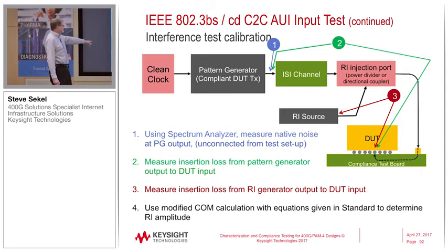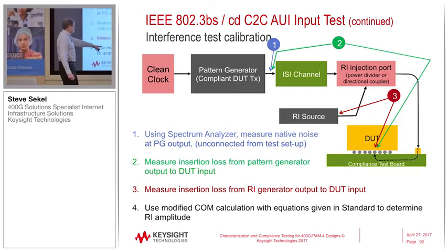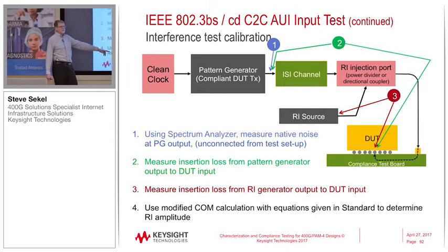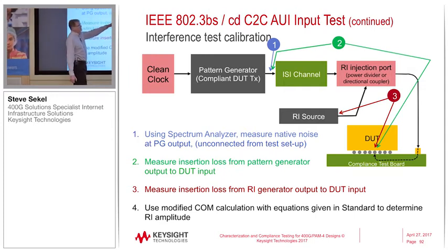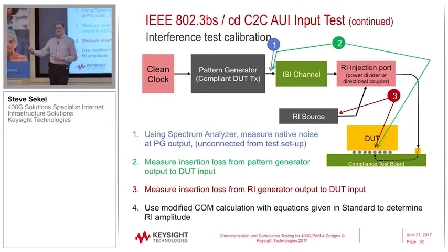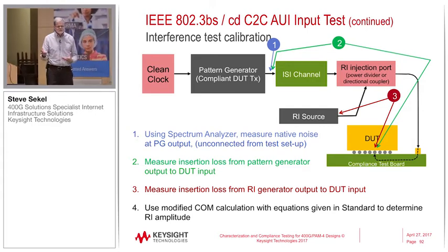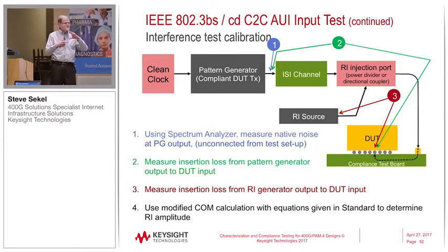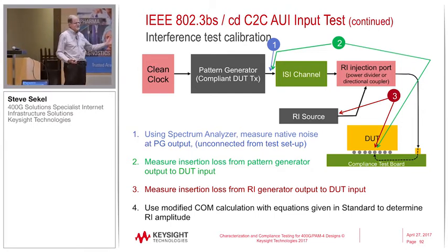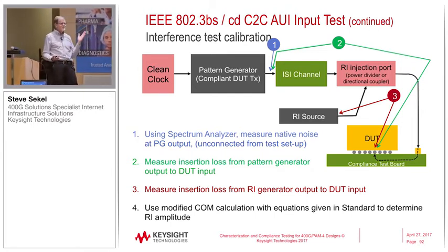So, why didn't they use another transmitter as the noise source? Well, that number works out... I don't think you can get enough noise out of it. That's the problem. They're putting it at the far end of the channel, and they're using the channel operating margin calculation to set that noise source to the worst case. This might be spec'd at 3 or 3.2 dB is what the COM number is.